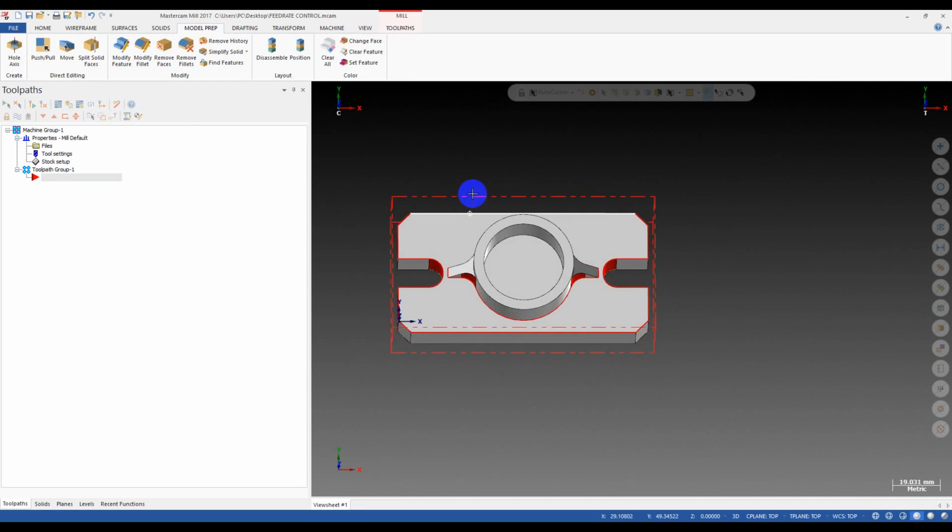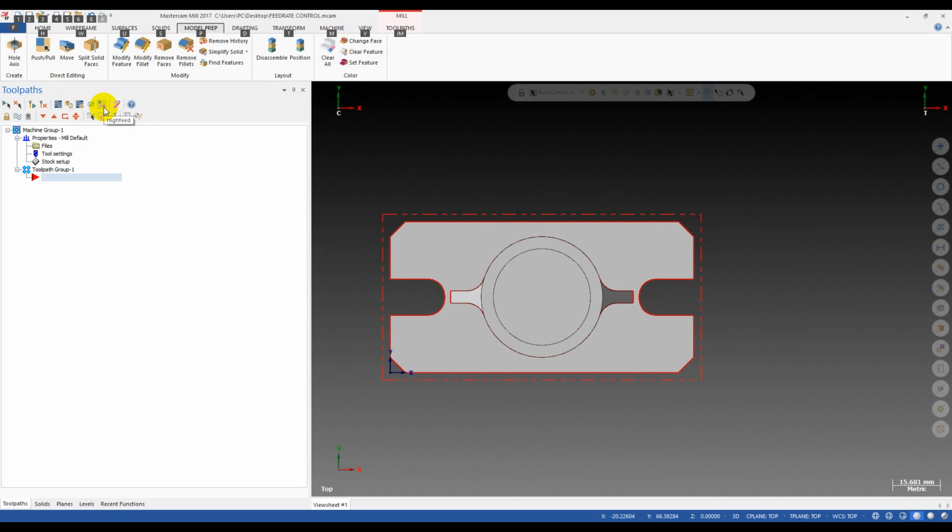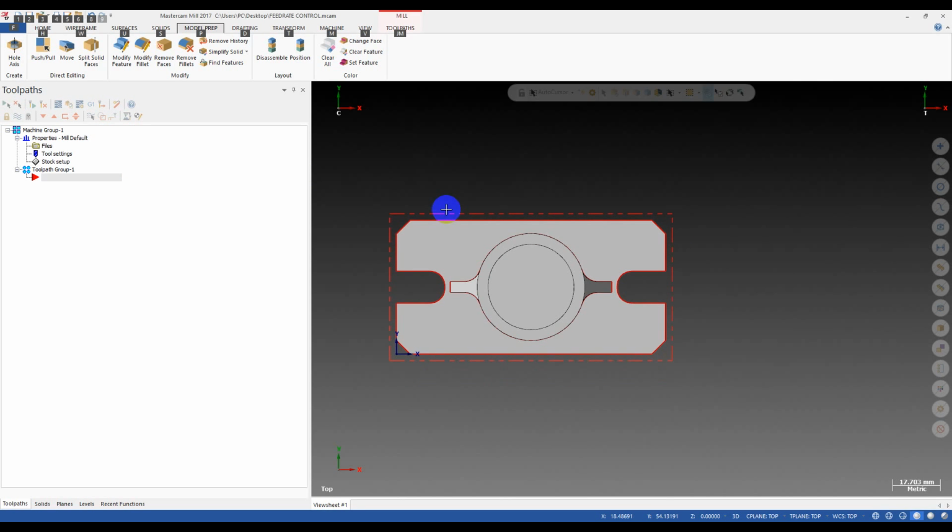Oh, sorry, you need to create a toolpath first. So I will talk about this first. The Highfeed function allows you to control the feed rate, to optimize the feed rate when you do the roughing operation or do a finished operation. Yes, this function work on both finished and roughing operation. It controls the feed rate. Yes, it can reduce the feed rate, it can increase the feed rate based on the value you define. Okay,